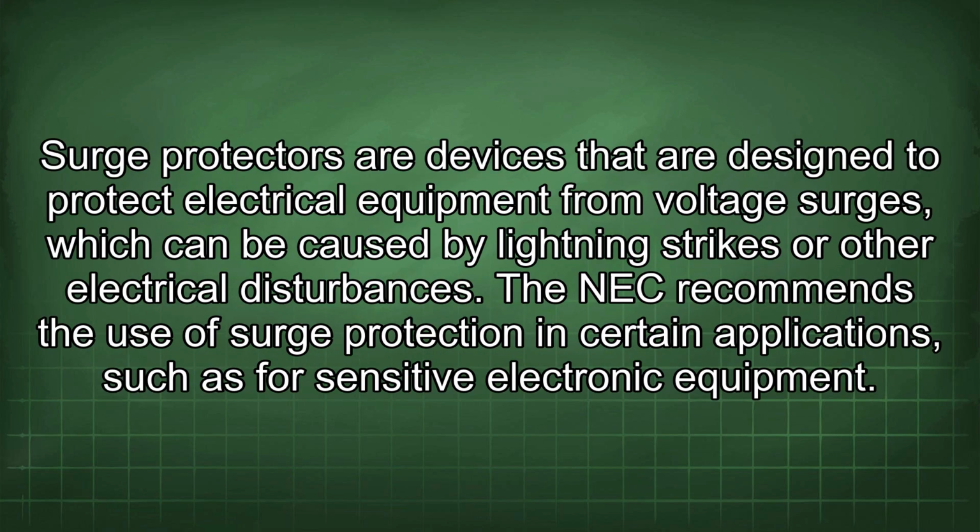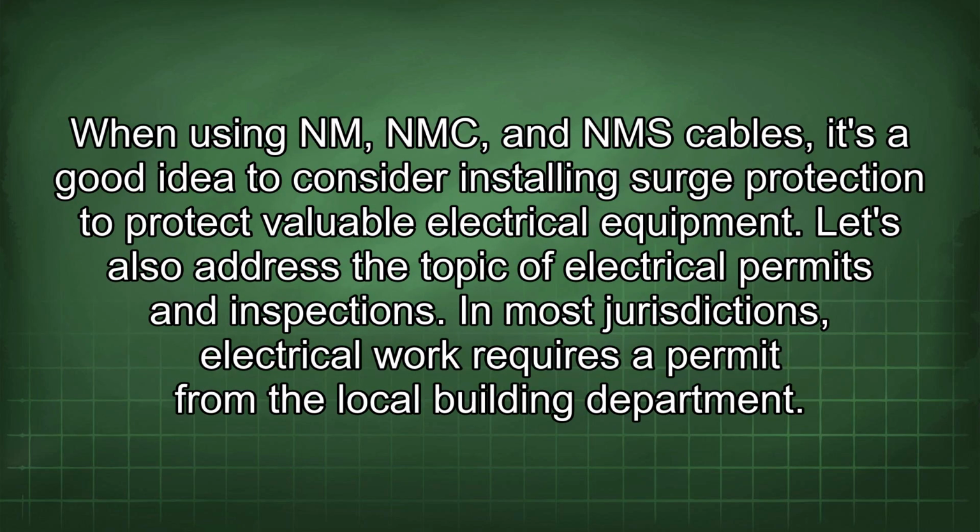Surge protection is another important aspect of electrical safety. Surge protectors are devices that are designed to protect electrical equipment from voltage surges which can be caused by lightning strikes or other electrical disturbances. The NEC recommends the use of surge protection in certain applications, such as for sensitive electronic equipment. When using NM, NMC, and NMS cables, it's a good idea to consider installing surge protection to protect valuable electrical equipment.